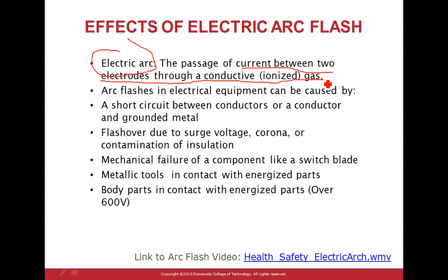Or like a transient, you have a high voltage. This distance is for 480, or 120. Now, what happens if you have a transient in your system? If this is 480, it could go as high as 4,000 amps for a very short amount of time. For 4,000 amps for a short amount of time, these will arc. A big arc jumps in here, the arc will escalate, and a big ball of fire comes out of that. That's your arc flash. So your job is to be ready for it.